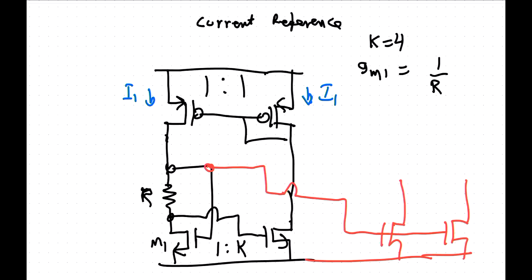So if you take the power supply, you power your chip, you move VDD away from ground like that. This node here will just stay at VDD, this one node here will stay at ground, and there's no current flowing in it. So that's no good. And that's the natural way that it's going to boot up.